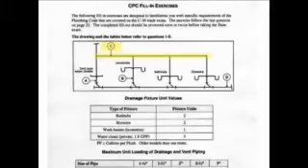So let's take a look and see what C is doing. C is venting the lavatories, the bathtubs, and the showers. But note that it is not venting the water closets. The water closets are vented by that vertical pipe in the left of the diagram. So make sure you don't include something that shouldn't be included or miss something that should be included.